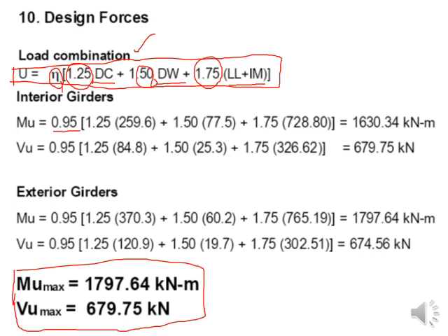maybe the second chapter of it, and in the load chapter you will see the type of loading experienced by different types of structures, and there you will observe that we can mainly categorize the types of loadings as variant and invariant. Okay, the variant ones are those that give you variations, like wind load, live load, snow load, like this, and the invariant means the dead loads, the loads that are not moving as such. So live loads are totally different, moving vehicular loads are totally different.